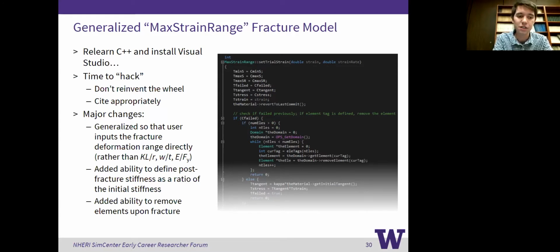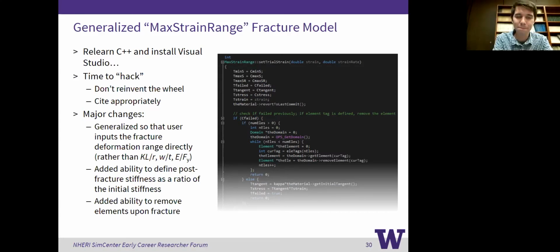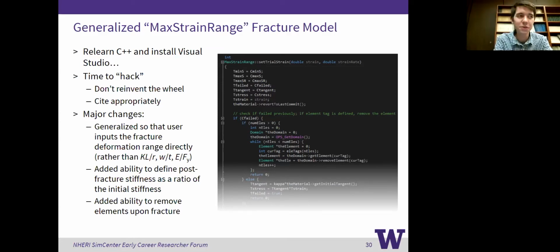Okay. Back to a question about the rigid elements you're using. What is the area of the rigid element at the brace location? Yeah, so the rigid element can have really any area. You're worried about E times A, right? That is the rigid stiffness. So if your E is very high, it doesn't matter if you've retained the original area of whatever section that is. You just want a high E times A.